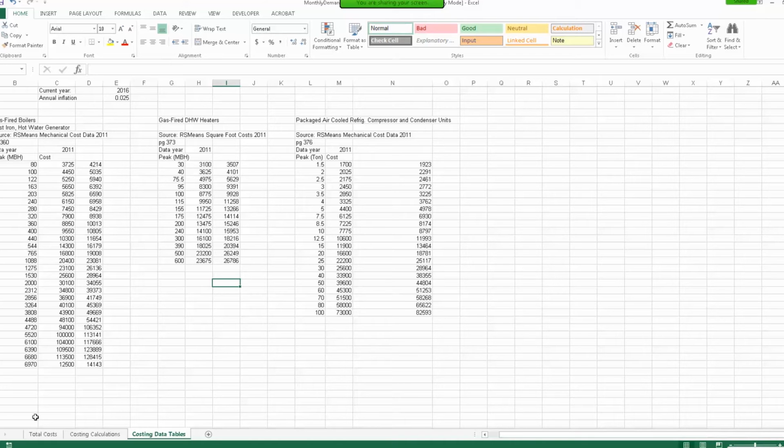So the boiler itself is going to have some connection with either a heat exchanger or going directly to those, like a fan coil system. It's those systems where you could change that out directly with a district heating system that has a heat exchanger. So if we can get right up to the point of the heating coil or the cooling coil on an air handler, those are the systems that we want to be able to compare against each other. Does it make sense to have our generation come from a central plant, or does it make sense to have boilers or domestic hot water heaters right in the buildings? That's where we're looking at the differences, and we've got to separate those costs out, and that's what we can find in these RSMeans documents.